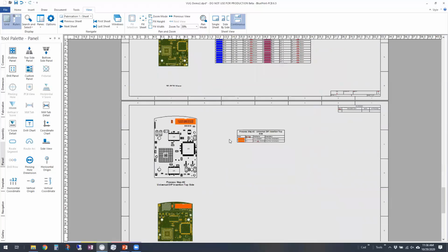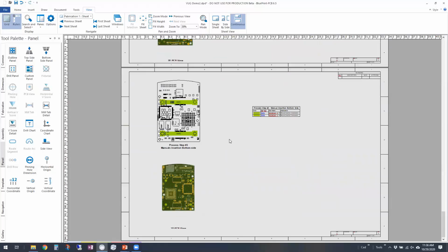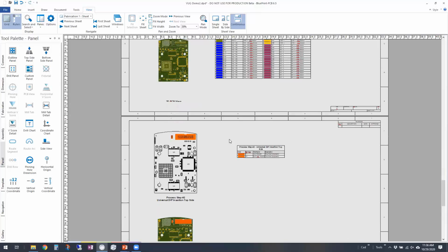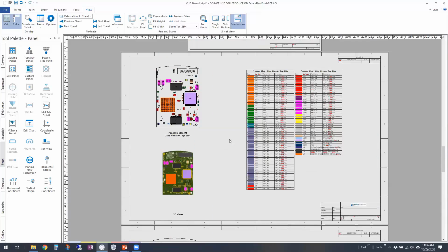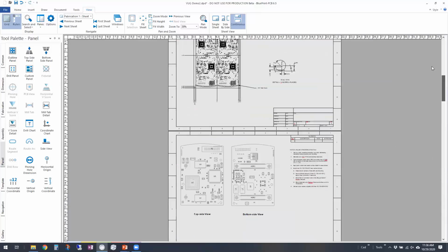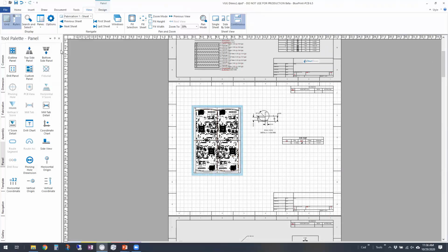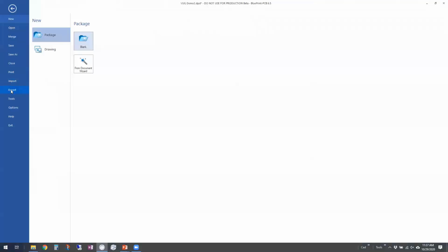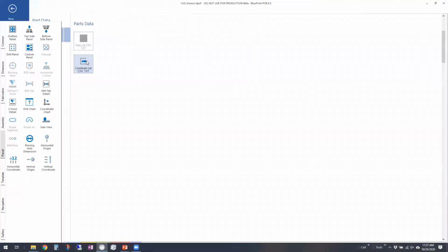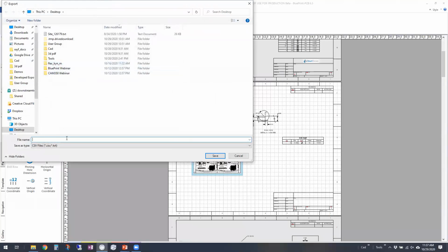So we've got variants and process steps here, okay? The reason I point that out is that I can actually do a Centroid report on this panel, first of all, and that would be as simple as export a coordinate list, all right? And let's just throw it out here.